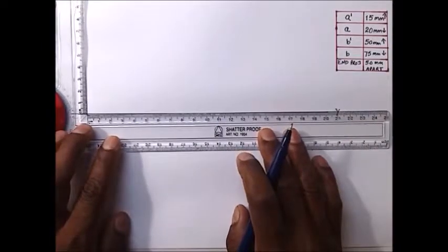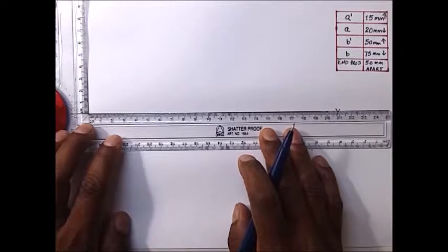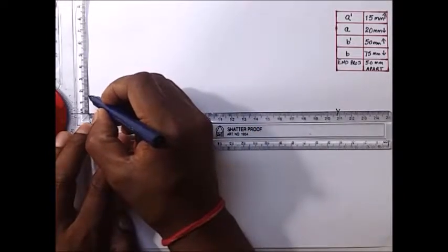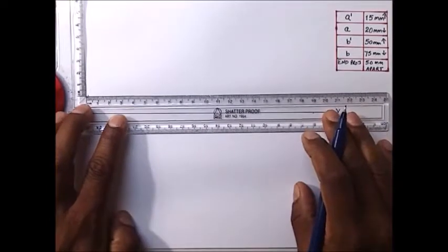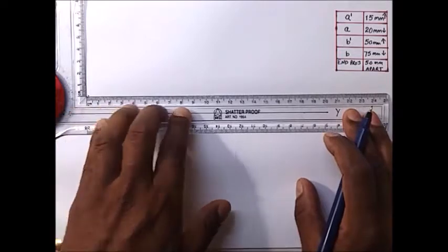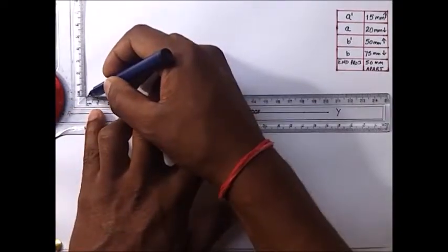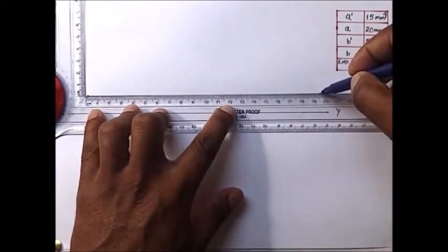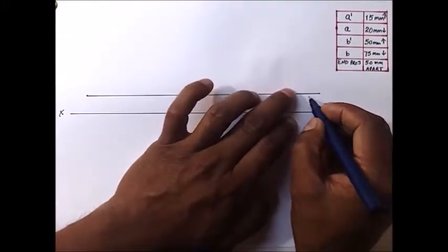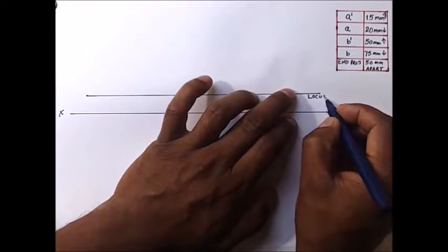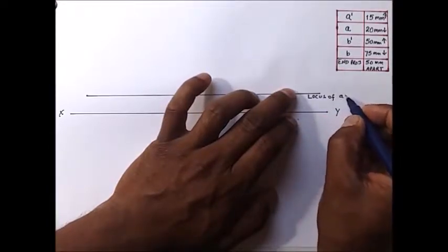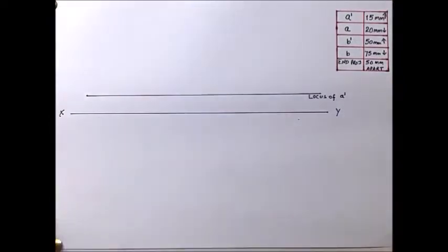So from the reference line take 15 mm and draw a parallel line to the XY. This is the locus of A dash.